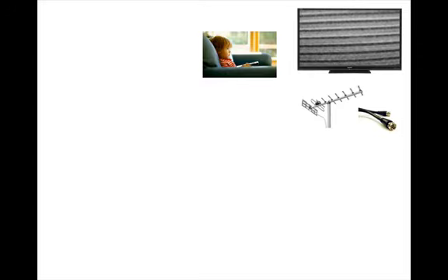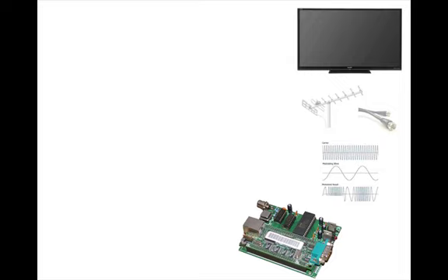But that kind of action wouldn't be indicated with just the higher level of understanding. However, even this deeper level of understanding is still only approximate. If power and signal are connected correctly, but the television still doesn't work, an even deeper understanding is needed. Repairing a television to solve that kind of problem requires understanding that the signals carried on cable or antenna include many different stations and require amplification, then extraction of one station from many others by demultiplexing, followed by separation of voice and visual signals, and finally driving the screen and the loudspeakers.